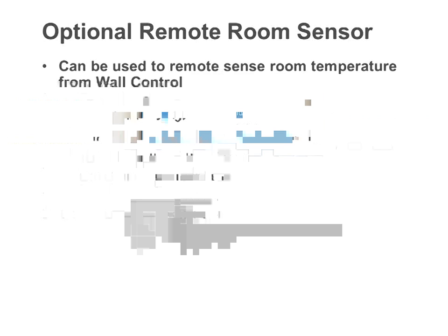The last sensor that would really be involved on a non-zoning system would be the outdoor air temperature sensor. If you have a communicating condensing unit or heat pump, this sensor is built into that unit and you do not need to do anything. It'll automatically send the outdoor temperature readings through the circuit board of the condensing unit to the furnace to the thermostat over that communication cable.